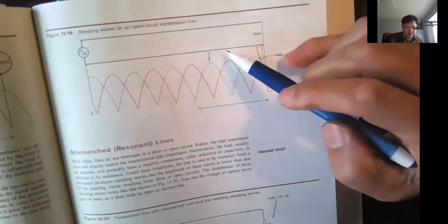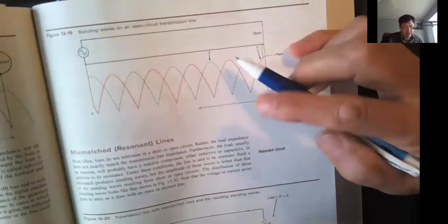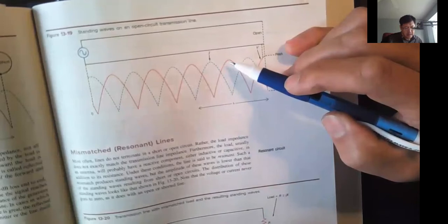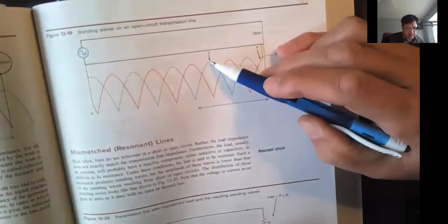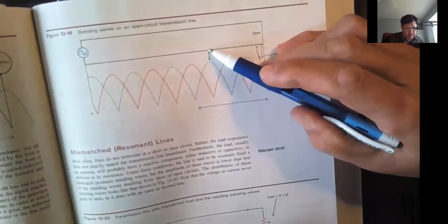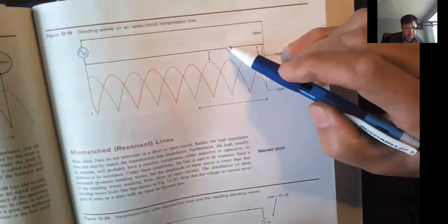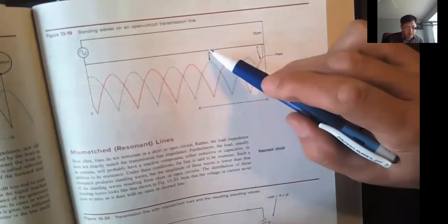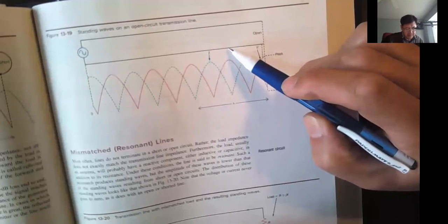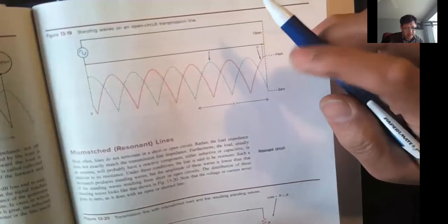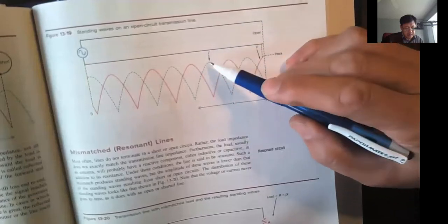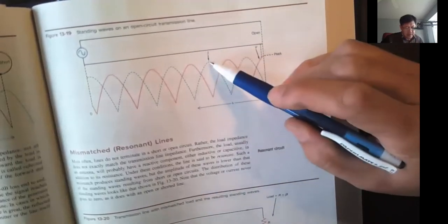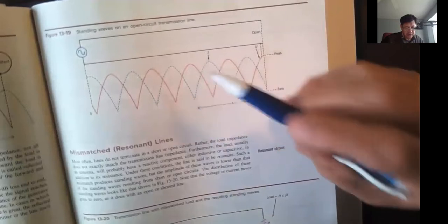So it's kind of strange. You have maximum potential, but the electrons are not moving. The potential has an up and down. That means AC. You have a maximum potential right here. So you have a maximum current here, and you have maximum voltage here. So the current is alternating, so does the voltage. So it's a standing wave. So that's the current. Maximum current right here and the maximum voltage when they have 0 current.